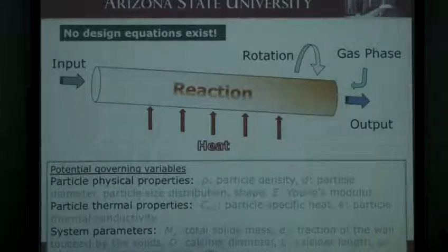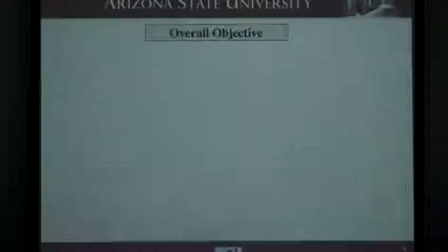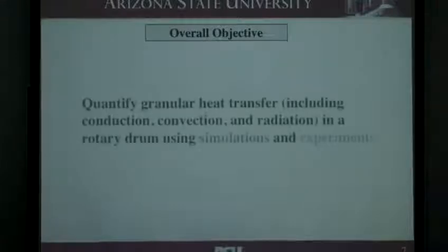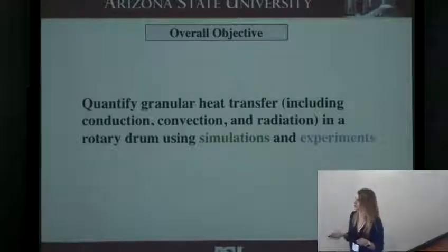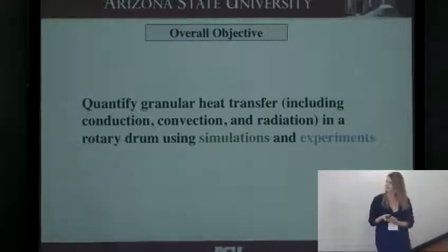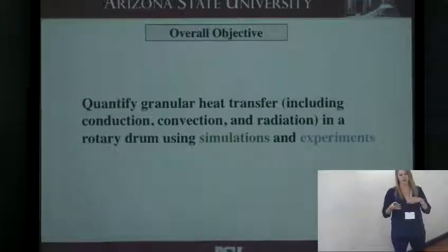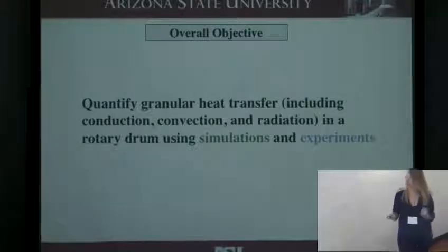And it's really difficult. Right now we have no idea in general how any of these really affect the heat transfer. So what happens right now in industry is they've just been doing it for a while. So you put whatever in, you get what you want out, and you don't really know what's happening in there. Okay, so the big picture overview of this work, and I'm just going to present a start to this, is we want to quantify granular heat transfer. That includes conduction, convection, and radiation in a rotary drum using both simulations and experiments. And the hope is that we can align both of those so that they can match.